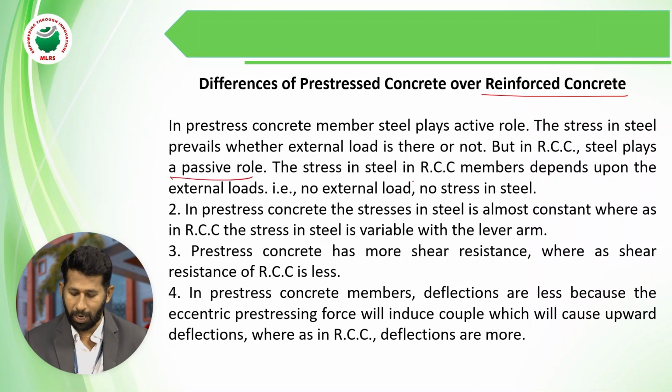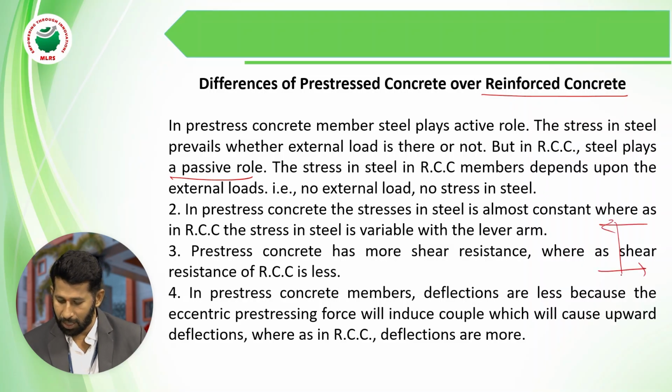The stress in steel in RCC members depends upon the external loads; no external load, no stress in steel. Second, in prestressed concrete the stress in steel is almost constant, whereas in RCC the stress in steel is variable with the lever arm. Lever arm means the distance between the tension and compression, so it is called the lever arm.